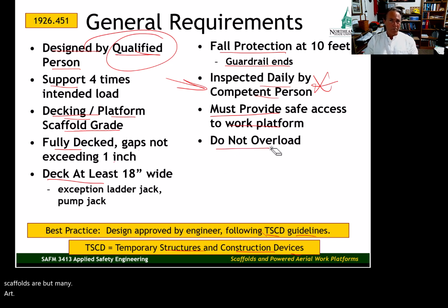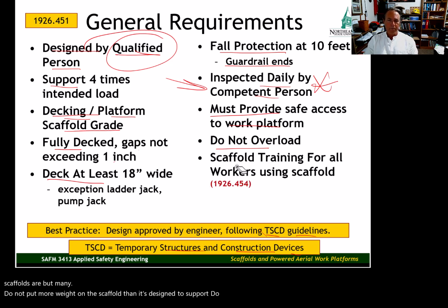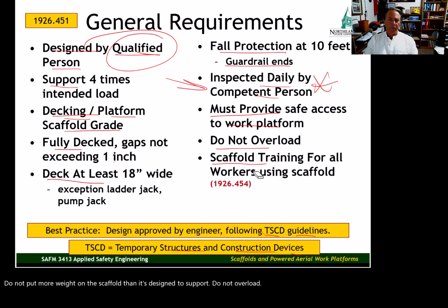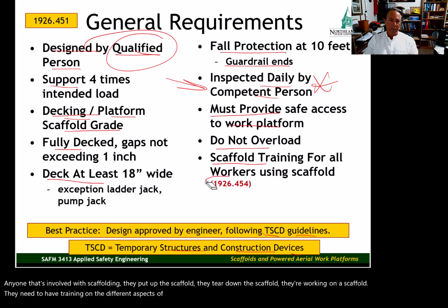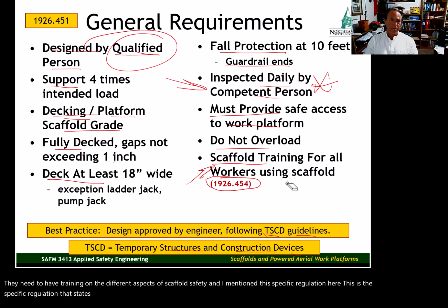Do not put more weight on the scaffold than it's designed to support. Do not overload. Anyone that's involved with scaffolding, they put up the scaffold, they tear down the scaffold, they're working on a scaffold, they need to have training on the different aspects of scaffold safety. And I mentioned this specific regulation here. This is the specific regulation that states this training requirement.